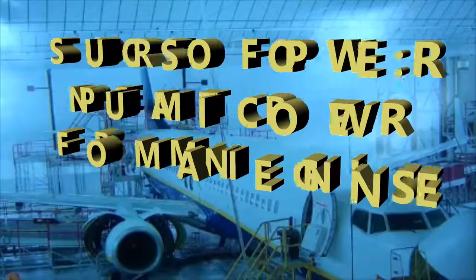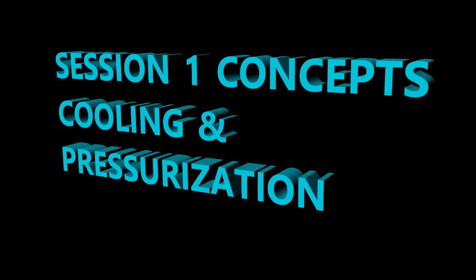Okay, so let's first talk about cooling, and then I'll move on to the pressurization concept. Here, with the cooling, we're talking about cool air, because the bleed air that's coming from the main engines is just not practical in itself, right? Because it's extremely hot. So there has to be a system to cool that air so that it can be usable. The cooled air from the cooling system is then distributed, after it's mixed, and I'll get into that in a bit, by 2 air conditioning packs.